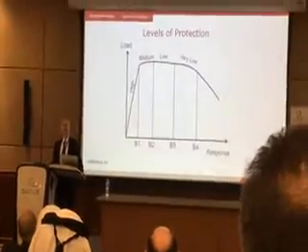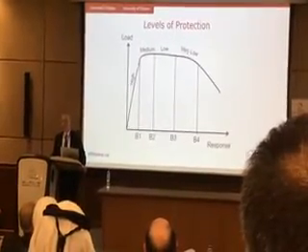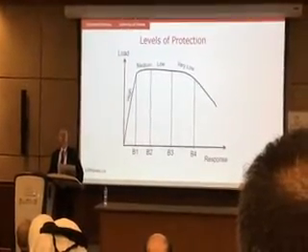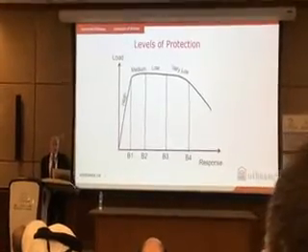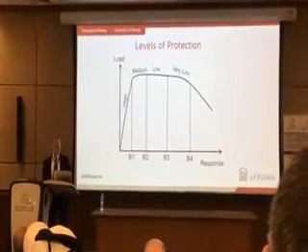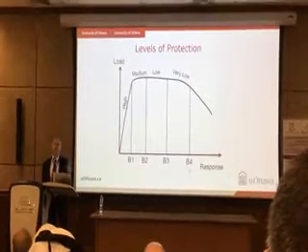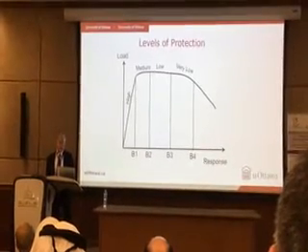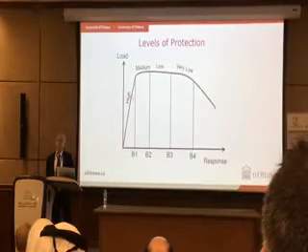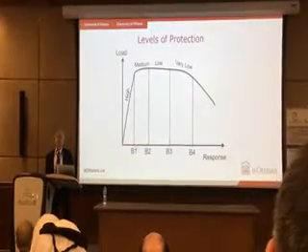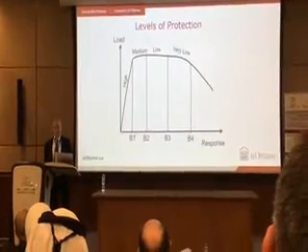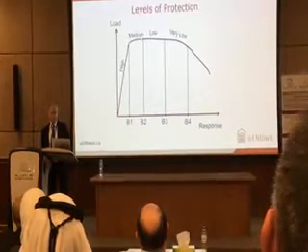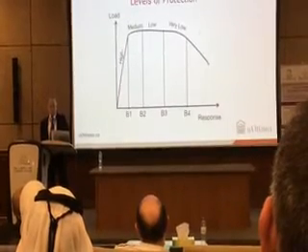Of course, these concepts are vague concepts until we look at force displacement relationships. Again, structural engineers look at numbers. Force displacement relationship, these quantities B1 through B4 are known as response limits. If I have high level of protection, and I just said that my structure has to remain elastic, so I design it for B1 ductility level, and B2 is medium level, which is used for life safety, and then you have low and very low is collapse.